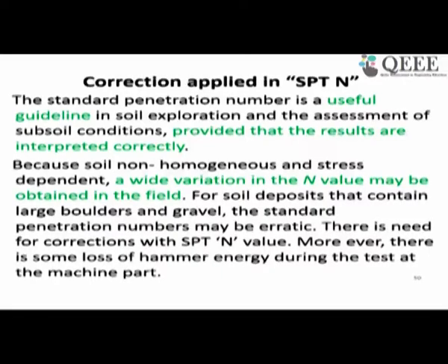Because the soil is non-homogeneous and stress dependent, wide variation in N value is expected. For soil deposits that contain large boulders and gravel, the SPT number may be totally erratic and may not be used.